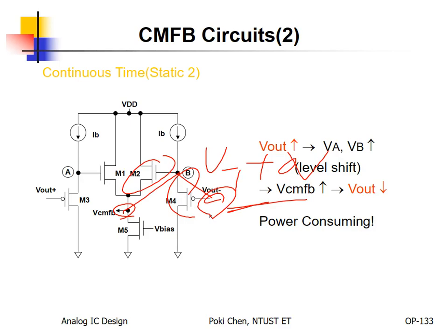Right? In practice, because this is a VTP, that is VTN, they are not the same. And also the delta V here and the delta V there, they are not the same. But you can try your very best to make them about the same. Bingo. Keep this in mind in the future. If you face some kind of challenge, how to lock the node voltage to the other? Okay, this is a very simple but a good idea.